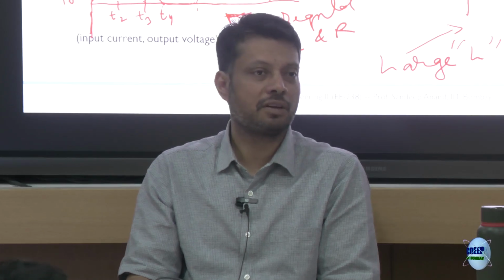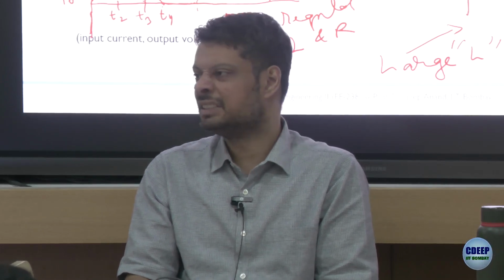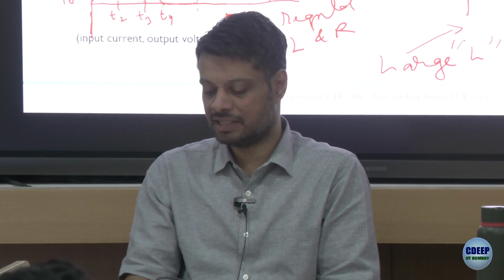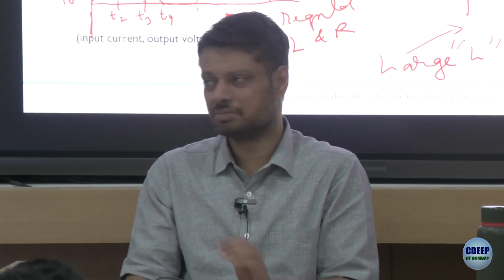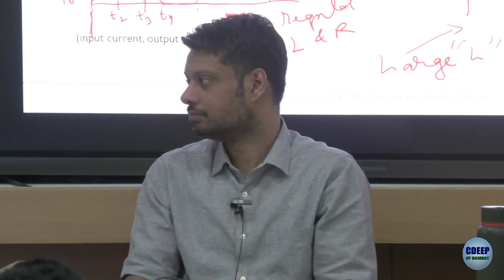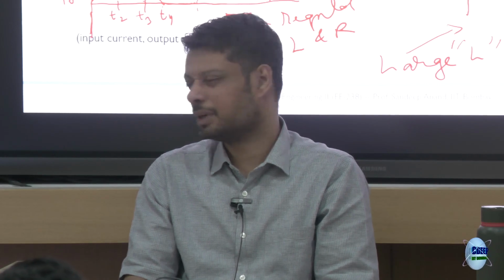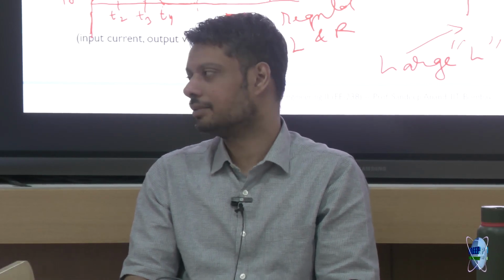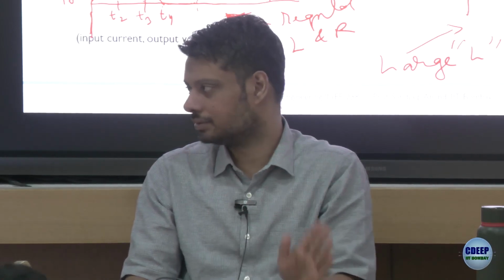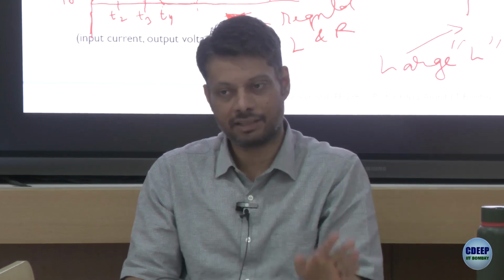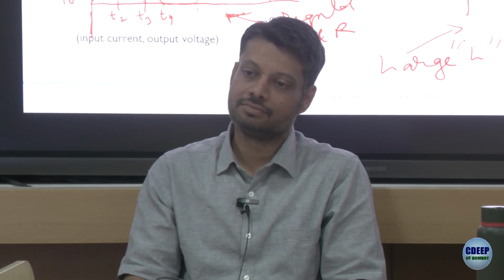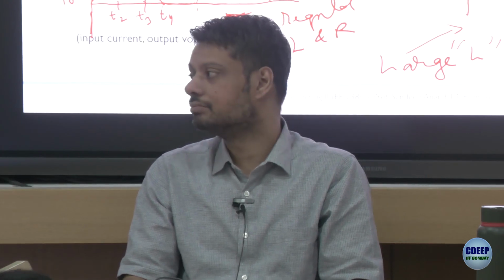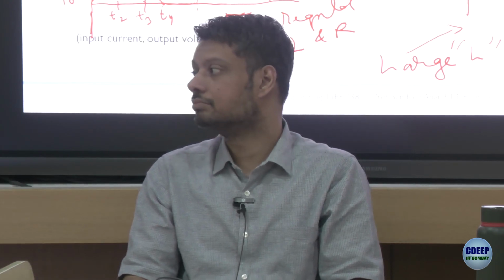I want you to physically tell me how things would change if I make the inductor value very, very large. Very large. It has more power to sustain the current for longer. Yeah, but it takes more power to increase the current. So L is very, very large. You are right. L is very, very large. The current practically remains, and we can counteract the diverse effect for longer to continue sustaining it.